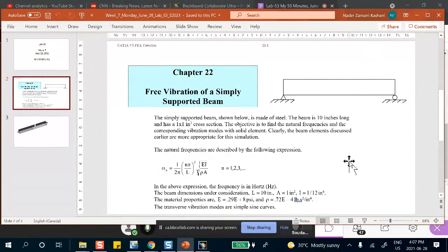You're seeing resonance at that frequency? That's very good. Yes, because if you had a motor sitting on this, a rotary, a compressor or a fan or something like that, and it turns at a certain RPM, and that RPM, that frequency matches the first natural frequency of this, then it will cause resonance. You're absolutely right. So we want to avoid resonance. There are other reasons, but the most common one that people should know is to avoid resonance.